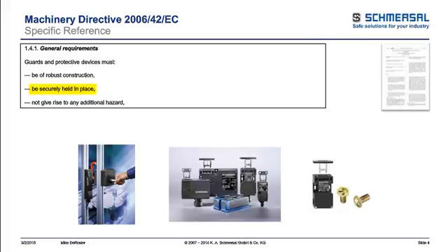Unscrewing an actuator or switch is not the only way of defeating, and you want to make sure that the device is not easy to bypass with other units or spare actuators, as well as not rendered non-operational, as talked about in this particular chapter.